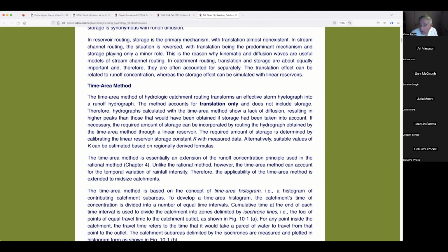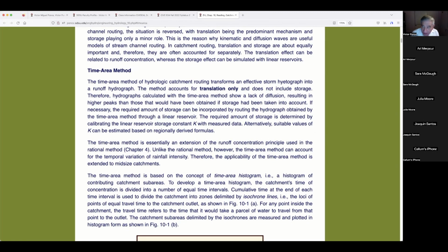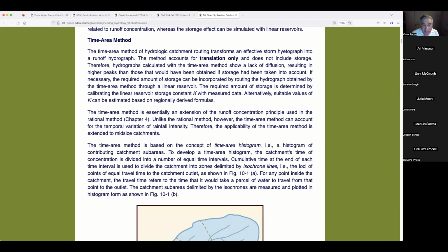Because we know the Hayami formula, which I believe I already talked about briefly to you. The Hayami formula has the slope, the driving slope of the flow, in the denominator. And once the slope gets to 0, the diffusion gets to infinity, and therefore infinite diffusion means the whole wave, if there was a wave, was obliterated instantly, and it became a sea of water. Okay, so that's to explain the concept of diffusion, because it's important, because we're going to consider it and we're going to calculate it.